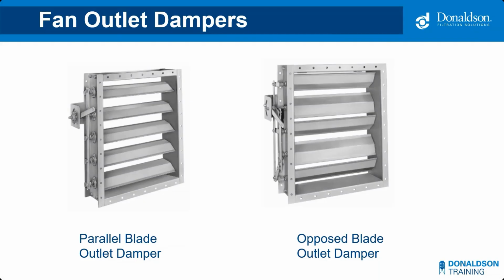The parallel blade outlet damper on the left is the lower cost of the two, but is fairly limited in performance, as the control arm movement is not proportional to the degree of control. It takes a pretty good arm sweep to adjust the parallel blade damper. So only specify this type when a small degree of control is required or when full open or full closed operation is needed, such as cold starts.